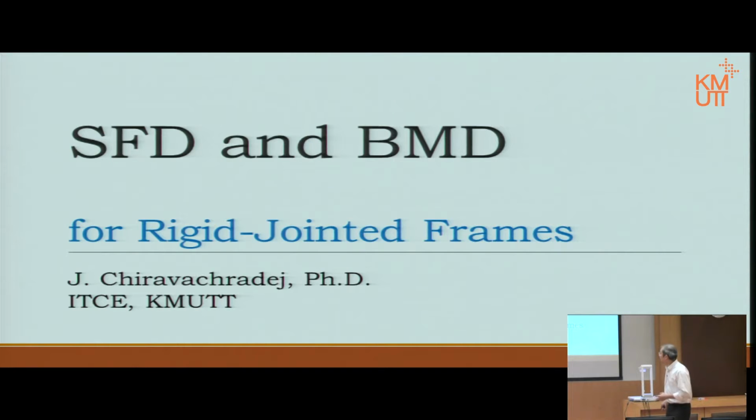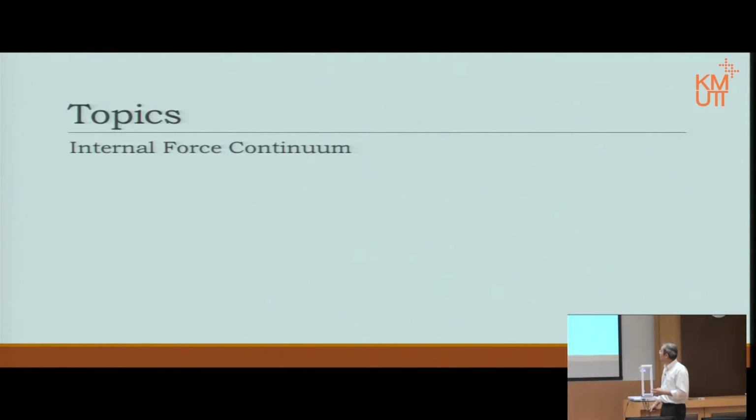The topic for today: because we're going to use the same theory on how to create the shear force diagram and bending moment diagram, the system of thought will be similar. However, the force continuum may be changing a bit, so we will talk about the internal force continuum in the case of a frame first. Then we'll see an example on how we actually use the two methods that we already learned, with the rigid jointed frame.